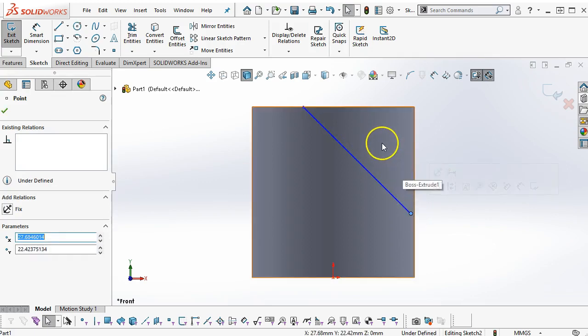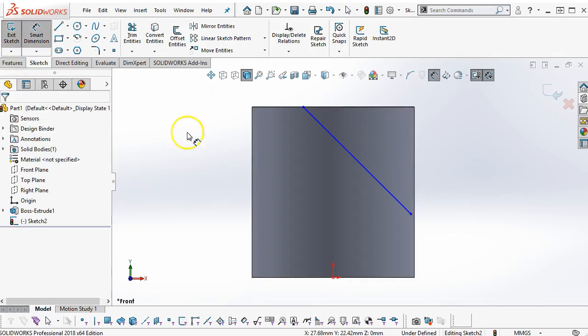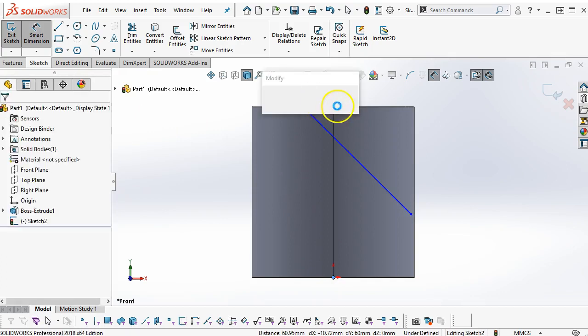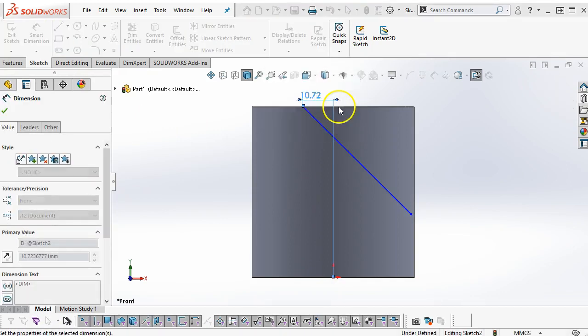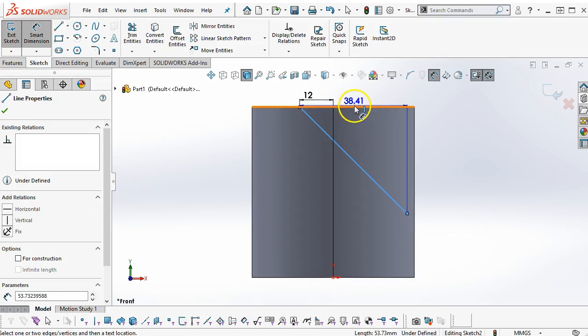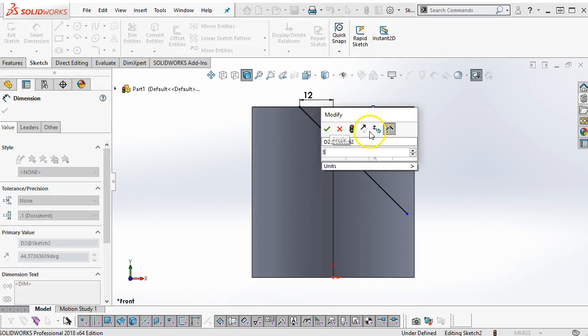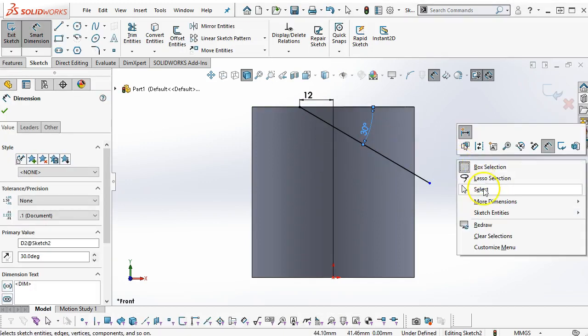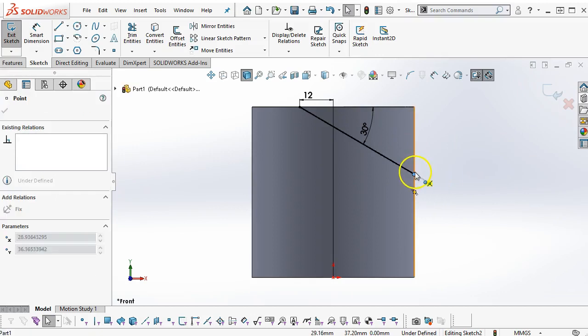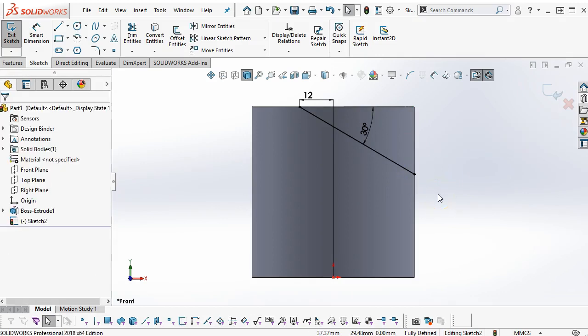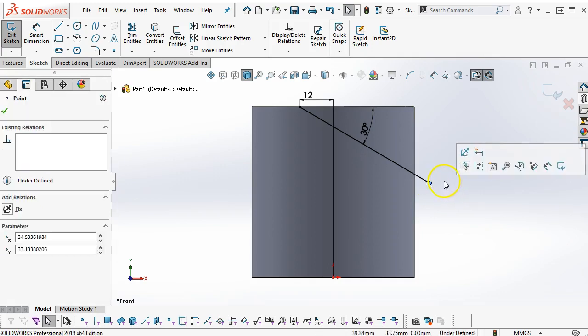And we have an angle of 30 degrees with a from center of 12. So if I position this correctly, I can go between the points without drawing the center line. 30 millimeters off of the top face, and then coincident back to the point. So do I need to make that fully defined? For an open profile, let's find out.